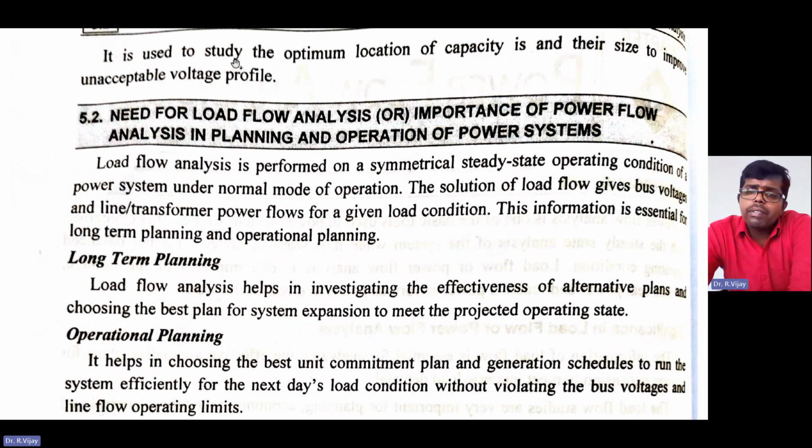So if the power factor reduces, in the companies, the industries will go for capacitor banks. They will inject the capacitor bank so that they make the lagging power factor leading, so that they maintain the power factor constant.